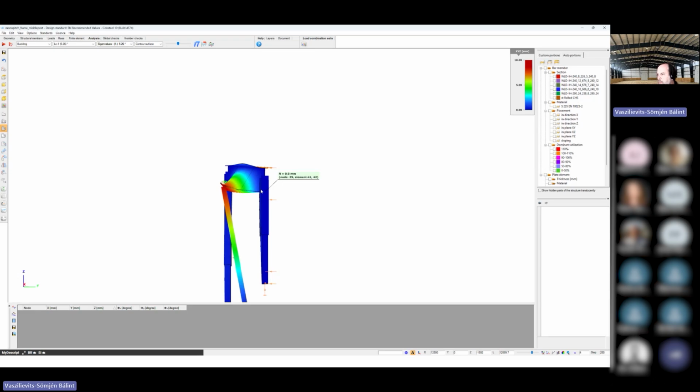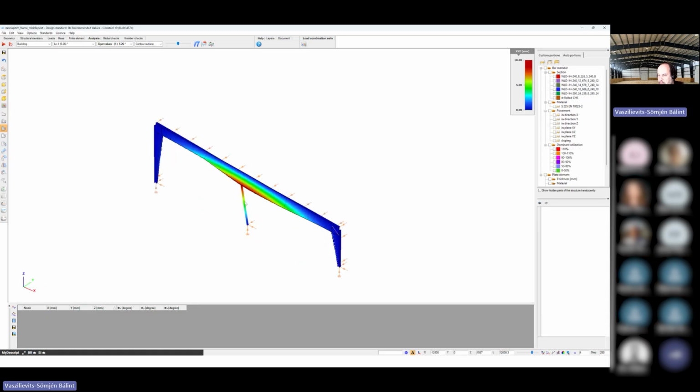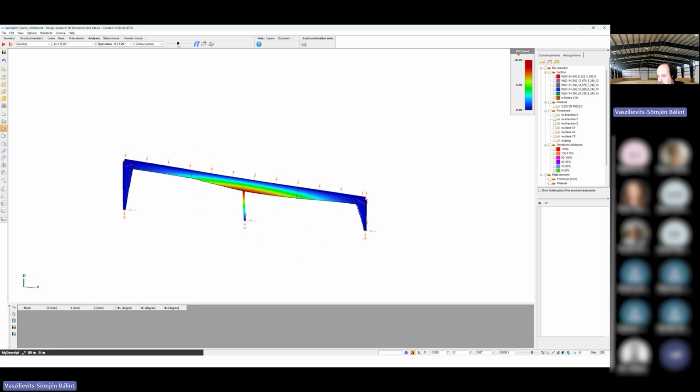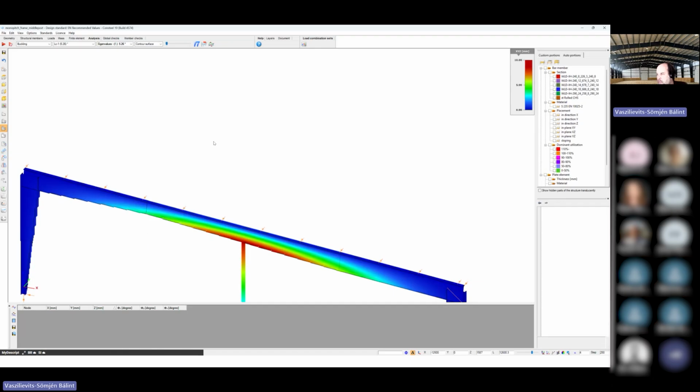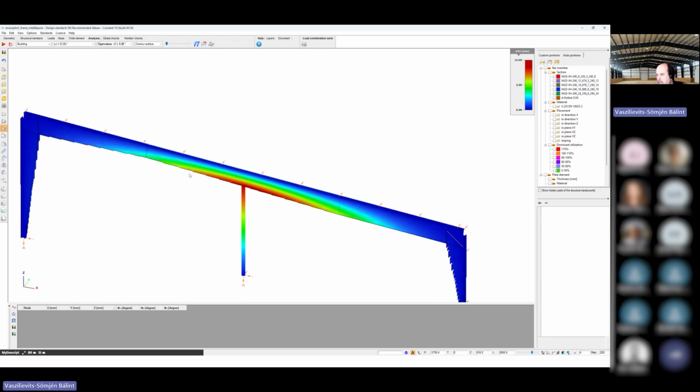I'm unfortunately quite sure that sometimes people forget this phenomenon, which is something very important, and you must be aware. Again, if you work with software different from Consteel, you will never see it. You make a model, and actually from this point of view, it doesn't matter whether you made the hinge connection location at the right level or not. If you use software which doesn't have this linear buckling calculation capability, you will never see such a direct result, especially one which has an effect on torsion.